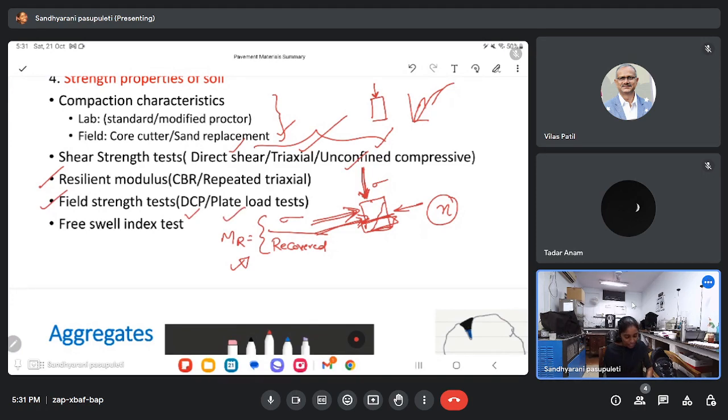to understand the field performance. And for the same soils, if I want to understand whether it has a higher amount of clay content than the recommended specification, how do we understand that? Using the pre-swell index, we can take some amount of soil, add kerosene to that, and also add water to that separately. Whenever there is water, these soil particles would be absorbing water, and their volume would be increasing.